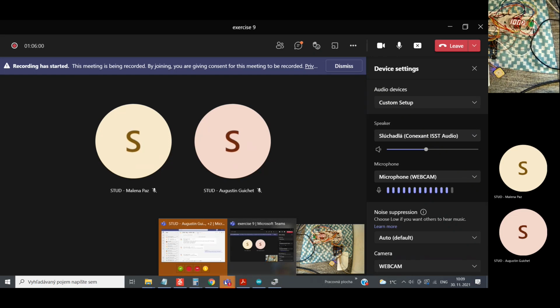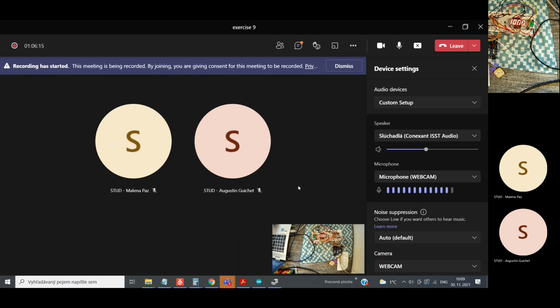You connect to Arduino only 5 volts to supply the GPS, the TX transmit wire from the GPS to the RX of the microcontroller, and ground of the GPS, and that's everything. It's okay.